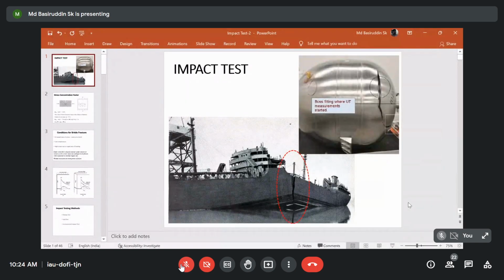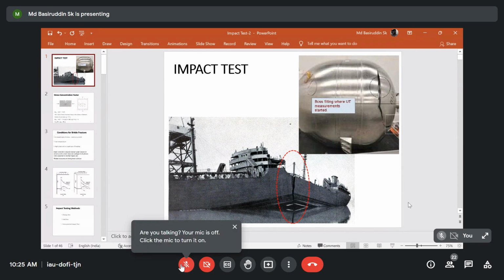They tried to correlate these things. Two important factors they found initially were the temperature, meaning at what temperature the ship was situated, and the impact loading, that is the ballistic loading, or a bullet impacting that particular ship, or heavy loaded things impacting the ship, so that led to this fracture.